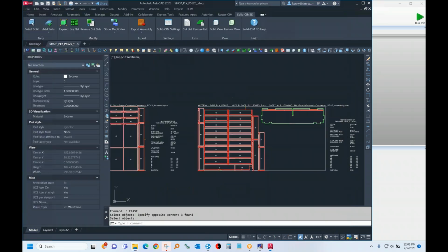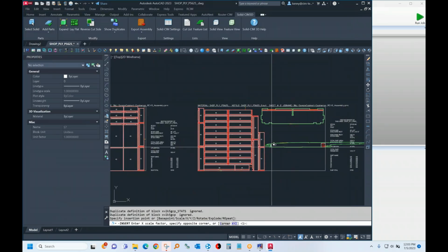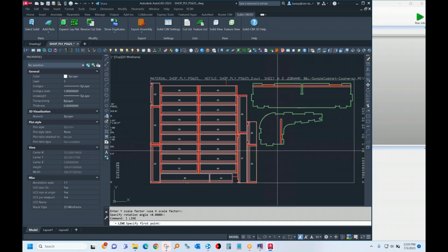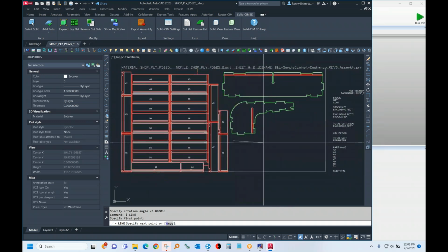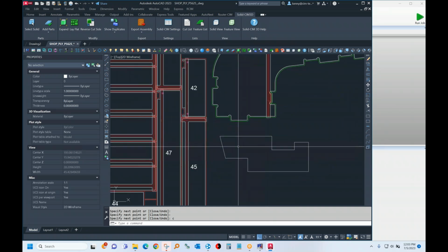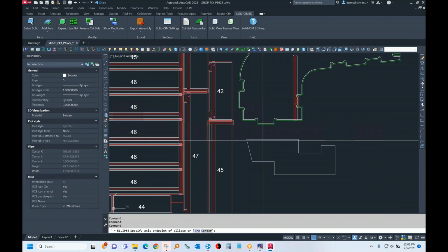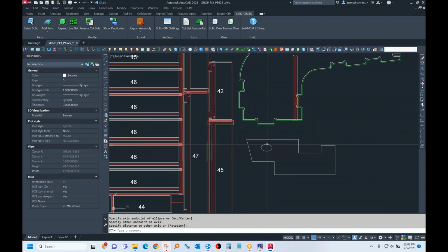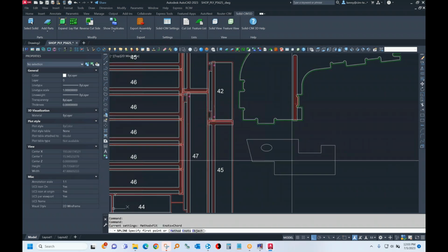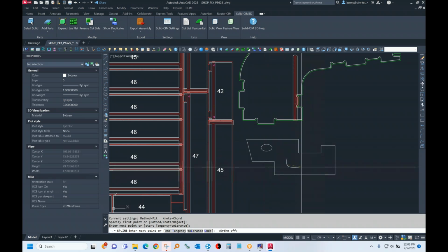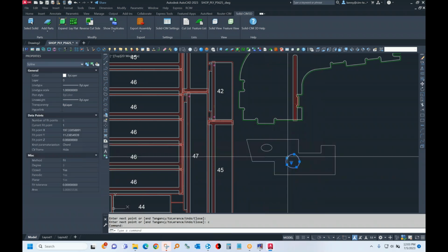You can use AutoCAD commands on this. So I'm just going to put 2 parts from another job in there and then maybe draw my own piece in here. I can just use an AutoCAD line command and draw another shape. And I like to show some potential problems that people encounter, like what happens when you have an ellipse or a spline. Router-CIM will convert those into arc segments, and it makes it much smoother, much easier for you.